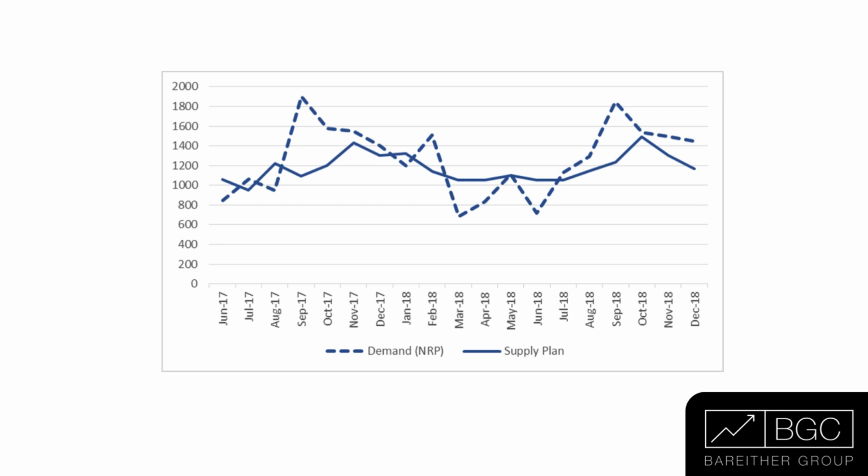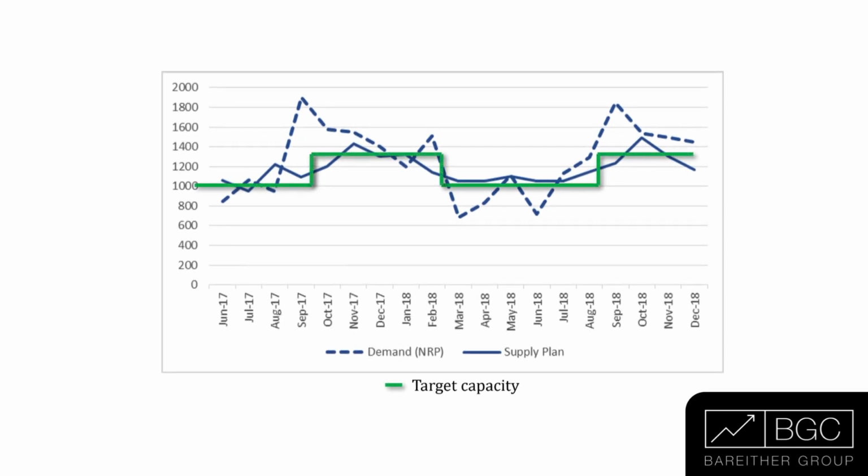In analyzing the demand, I recommended to that client that they create 2 levels of standard. Their highest demand quarters were actually the first 3 months of the year, January, February, March, and the last quarter of the year, October, November, December. So we created a standard with a higher demand, a shorter takt time, to operate in those 6 months of the year. And during the middle of the year, quarter 2 and quarter 3, over history, we showed a lower demand. So we created these 2 levels, a high demand and a lower demand, each to run with a constant takt time and pre-balanced standard work so that they could decide when to switch from one to the other.